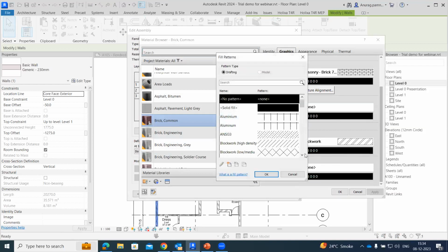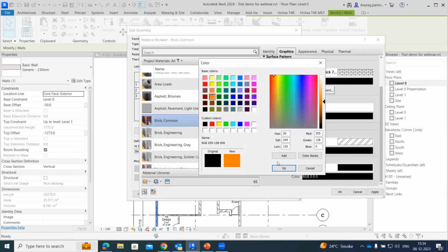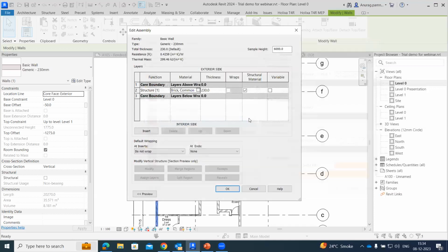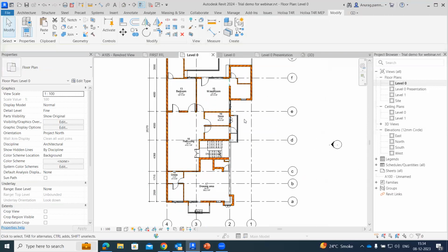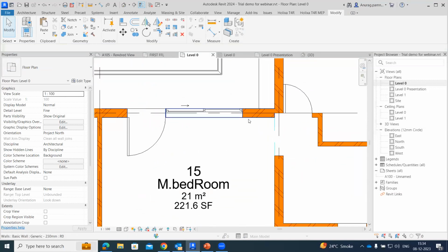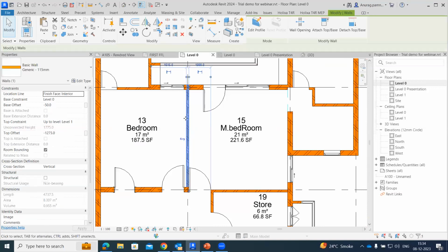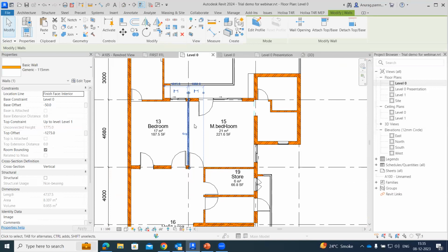Under the background, I would just play with solid color, and I can change any of the colors to make it more presentable. Like this can be easily understood with design and the denotation of colors, that all the color which have orange as a background color is 200 mm thickness wall. So here likewise, this is 100 mm, but yet it is being presented as 200.